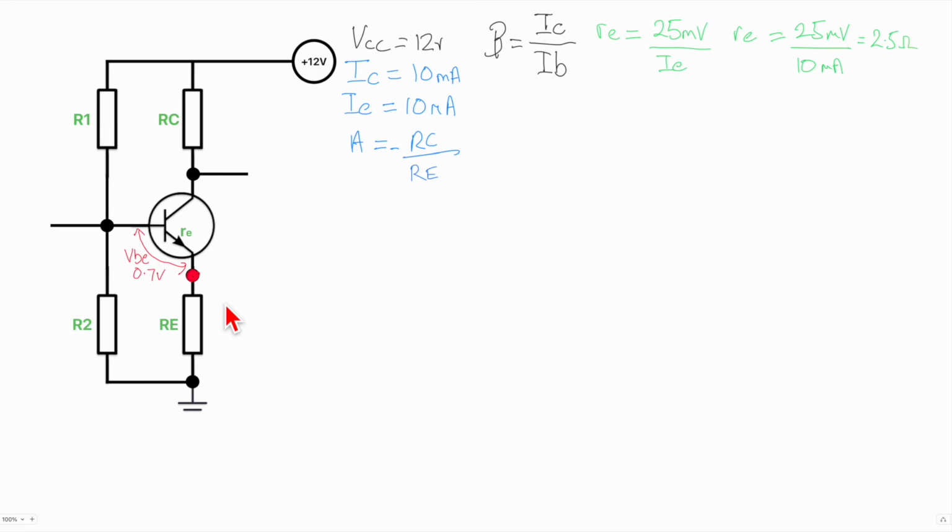The other interpretation is that you wouldn't put a volt on, you'd put 10% of the VCC, of the DC power supply. When I designed my amplifier, that's what I did, which is about a volt. It's 1.2 volts. So that's what I wanted to achieve, and so VE, the voltage on the emitter, will be 1.2 volts.